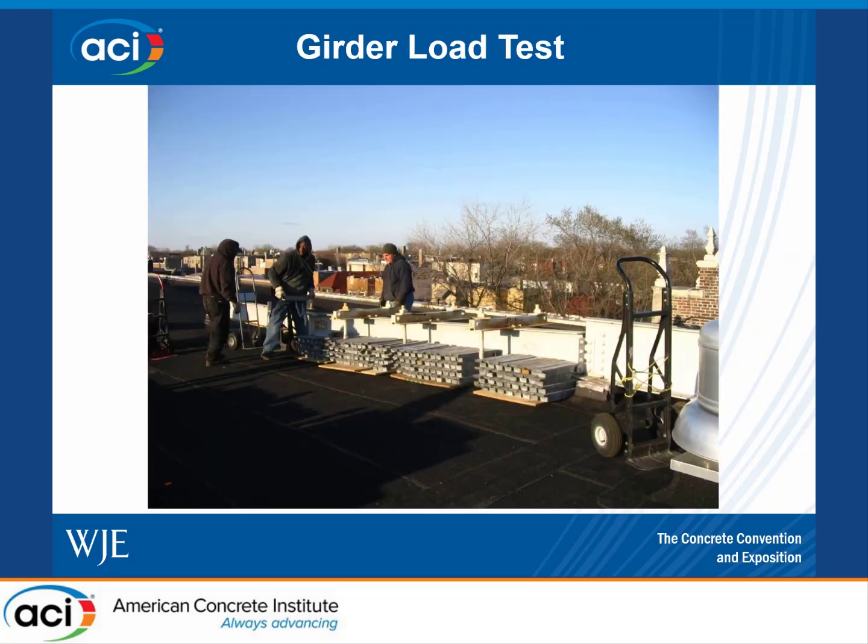For the girder tests, we recreated a line load over the tops of the girders using lead ingots. The typical girder test was about 23 to 25,000 pounds line load over about a 15-foot span for the girders.